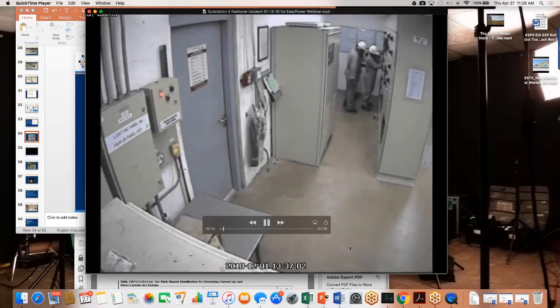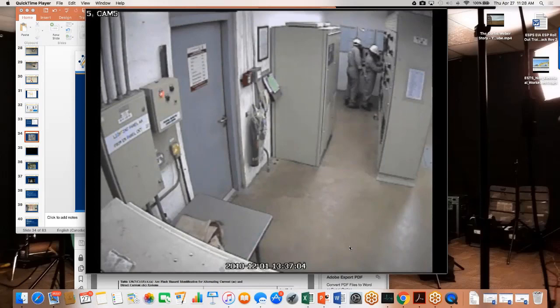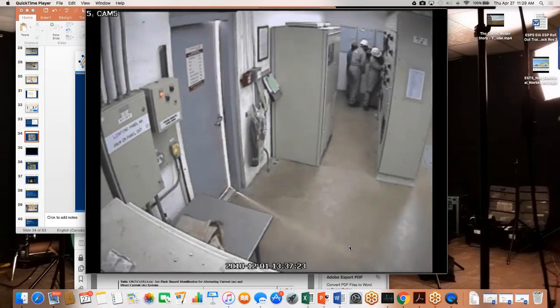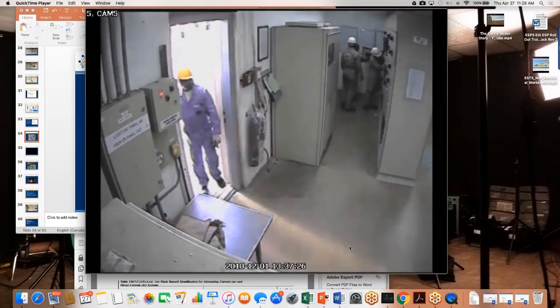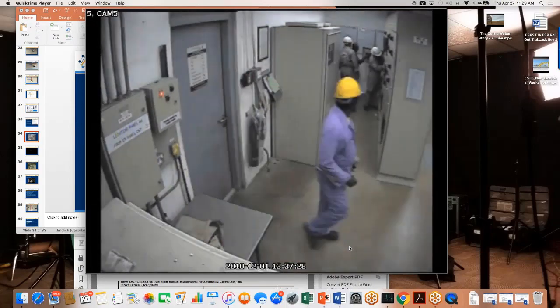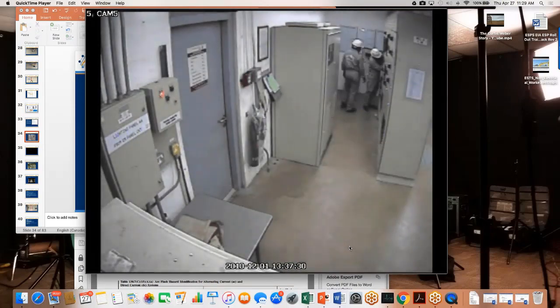This is high risk because we have a worker doing energized repair and alteration in an MCC starter bucket, and he has no formal arc flash risk assessment or shock risk assessment. The two other workers are confining him. The two other workers are actually talking over top of him. His human performance behavior is affected, and he is not on task. Another worker walks into the scene, and could also walk into this work environment because there's no electrical work zone with red tape created. The arcing fault arc flash is coming, right?